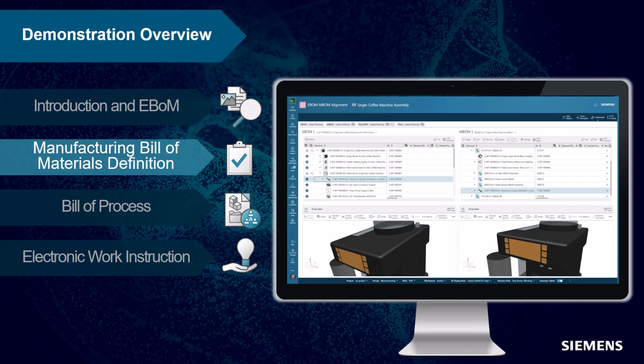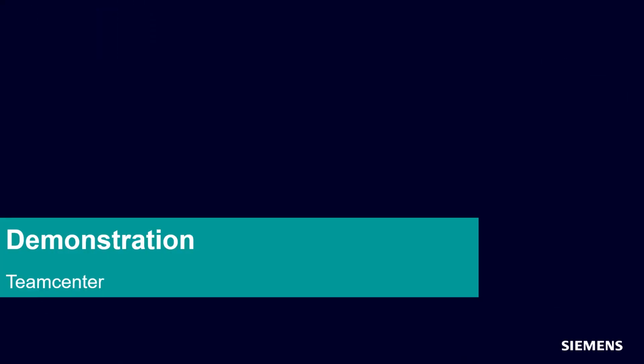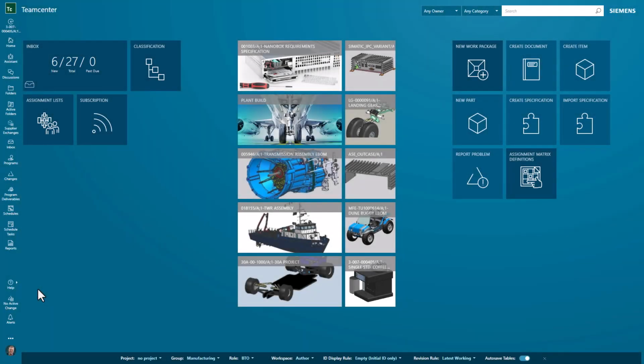The demonstration itself will first review the current MBoM. We will see that the components making up the MBoM are the same ones used in the EBOM but structured to suit manufacturing purposes. We will also see, like the EBOM, this is a 150% MBoM and can be filtered down to 100%. We will then show you how the MBoM is generated from the EBOM and how updates in the EBOM are considered. We are currently logged into Teamcenter as a user who is from Manufacturing Engineering.